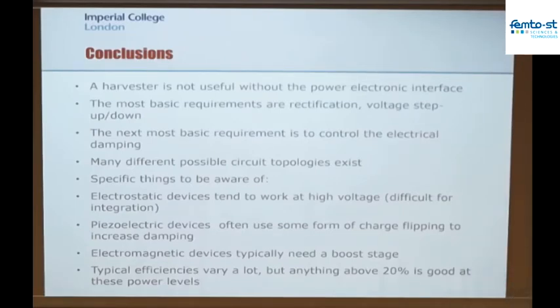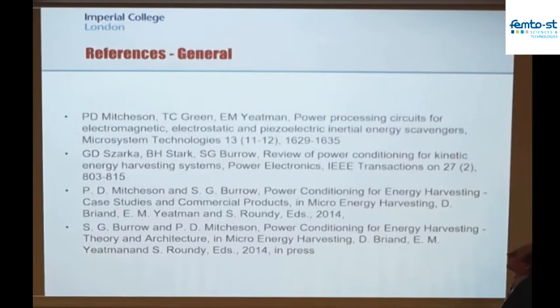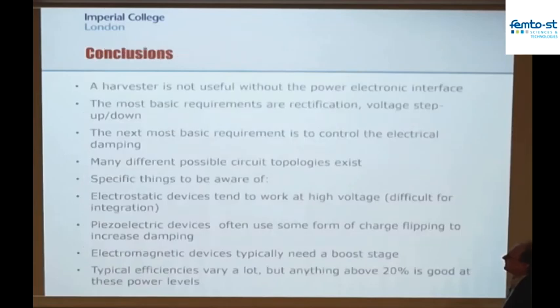And we can control the current in the electromagnetic harvester or the voltage on the piezoelectric or electrostatic harvester to try and maximize the power density. So we look to produce these switch mode power conversion circuits that interface to our harvester that try and operate in the most efficient way possible so that the energy loss in the circuits is very small, but also at the same time that we enable circuits that can give us the maximum power density by optimizing the force on the transducer itself.